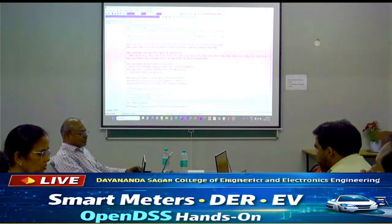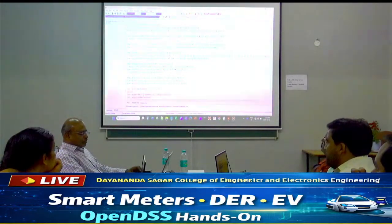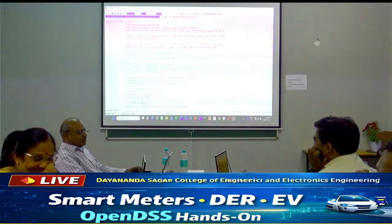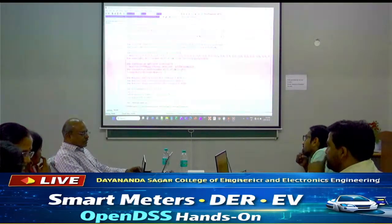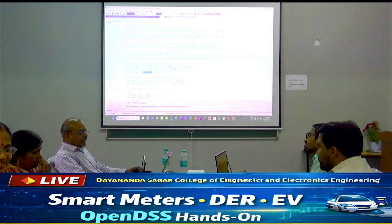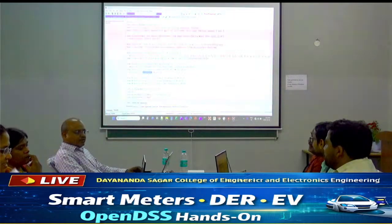So you have a PV system here connected to the load bus at 12.4, so whatever the kV of the load, and then it's a 10 kilowatt PV system, power factor 1. And then here you are defining daily equal to PV. So whatever we defined as the load shape here, we are giving that.